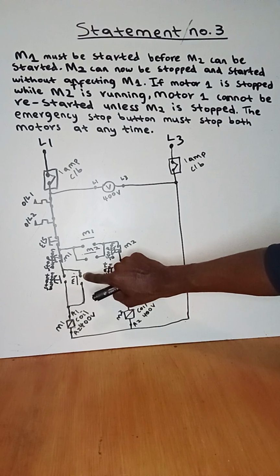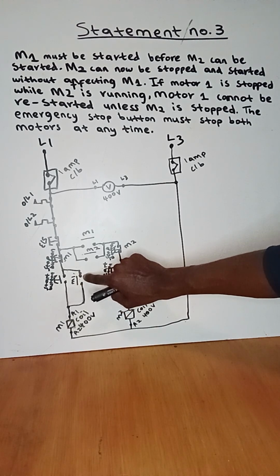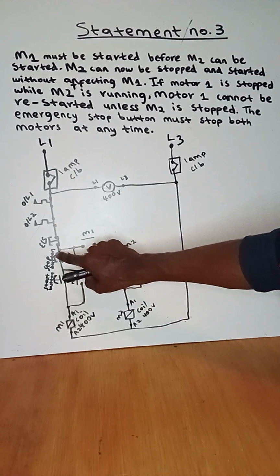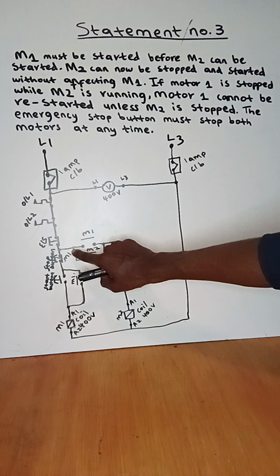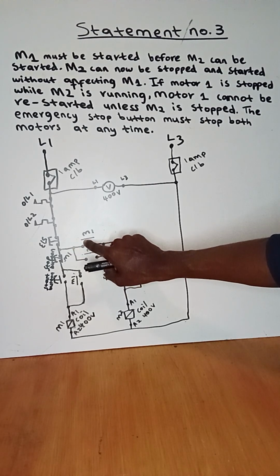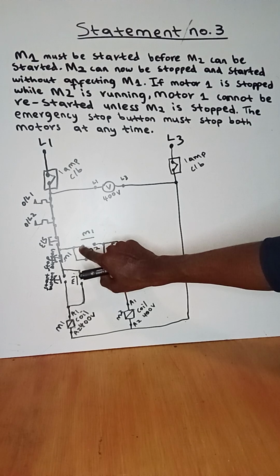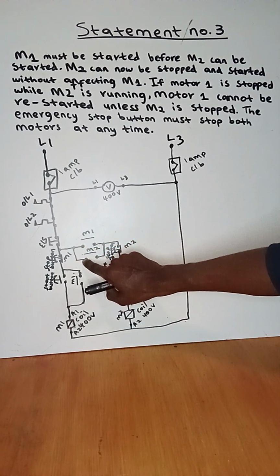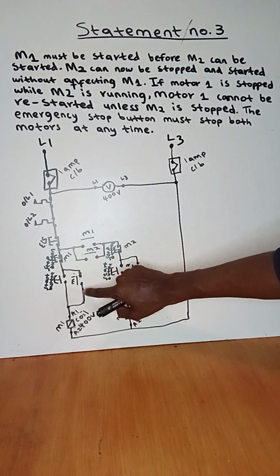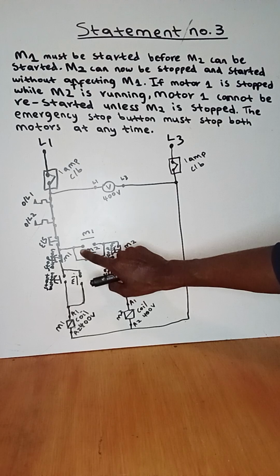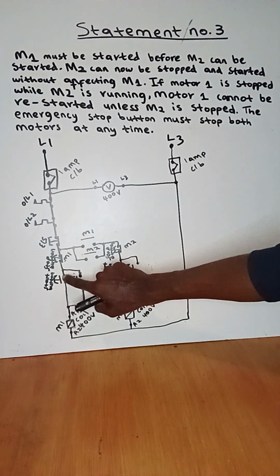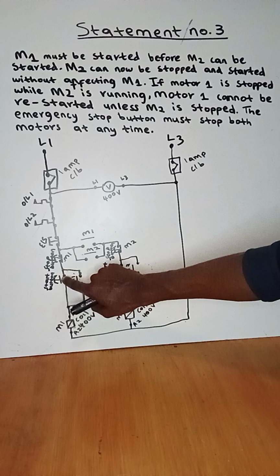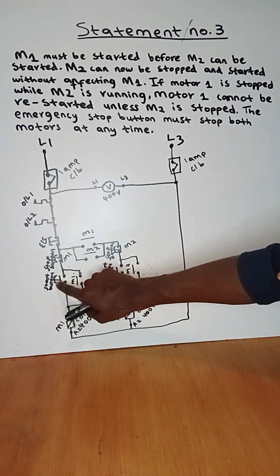will flow all the way to the contact of motor 1 and finds it normally open, which means current will be stuck here. And then from here, current branches again all the way to the contact of motor 1 normally open, current will be trapped here again, and also current will be trapped here in the contact of motor 2 normally open. So our current is trapped from 4 points, this here, here, here, and here. So since here it is trapped before the start button, it means it allows us to press the start